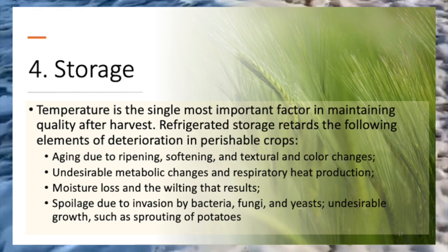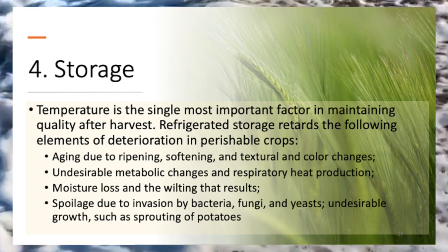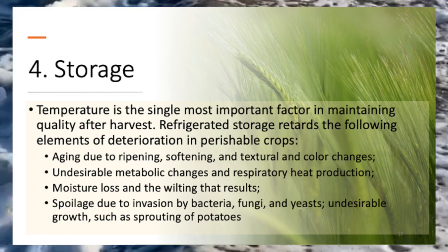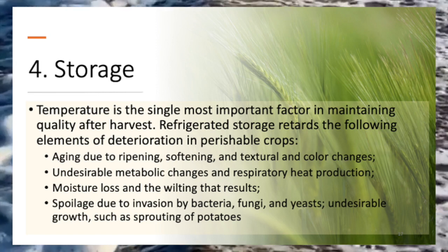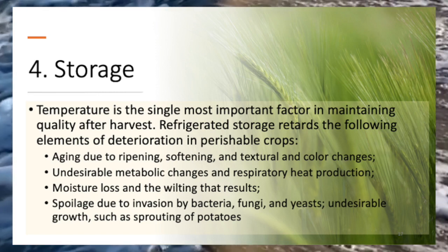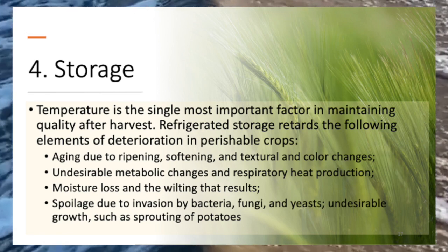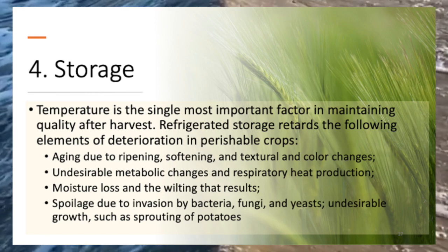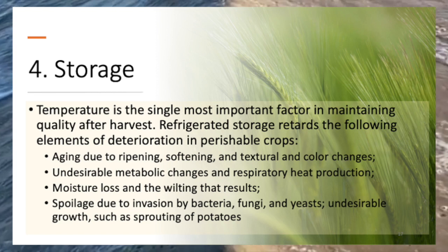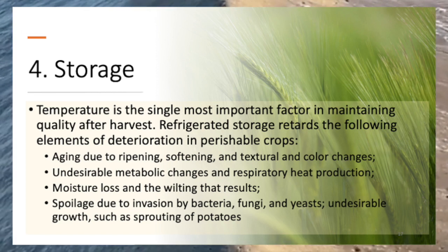One of the most important functions of refrigeration is to control the respiration rate of the crops. The higher the temperature of the storage, the higher the rate of respiration. For refrigeration to be effective in postponing deterioration, it is crucial to keep the temperature in the cold storage room as constant as possible. The storage room should be well insulated and adequately refrigerated and allow air circulation to prevent temperature variation.